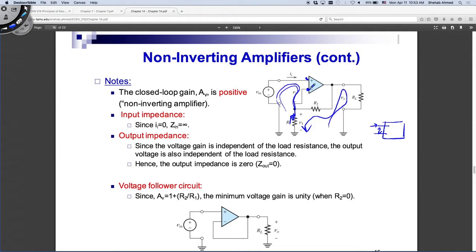But when I do this feedback properly, then I do what is called negative feedback. Negative feedback means it's feedback that drives this voltage difference to 0, right? So when the input source was connected previously to the negative side, I brought in a negative value. When now the input source here is connected to the positive terminal, if I don't have feedback, what will my output look like?